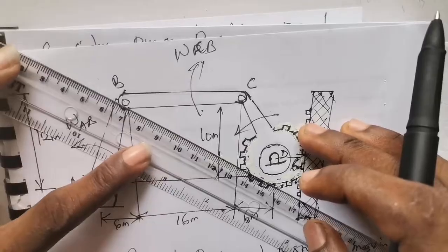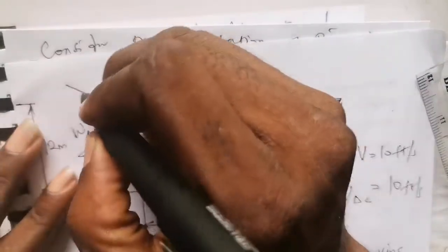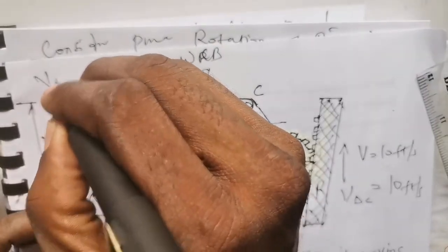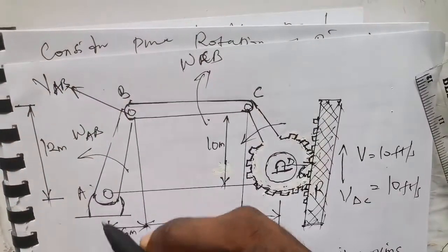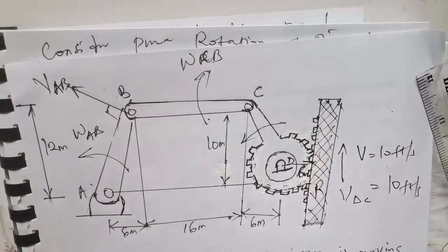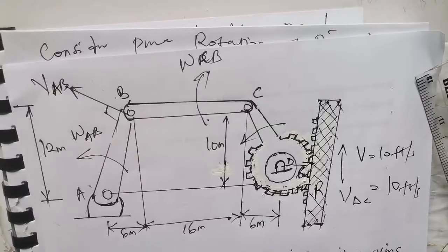At 90 degrees to this surface, you have something like this. So this is our velocity V A relative to B, the relative motion from A down to B, and it must be at 90 degrees to this surface as can be seen. So let's pick out the free body diagram of arm AB and consider the pure rotation of that arm.